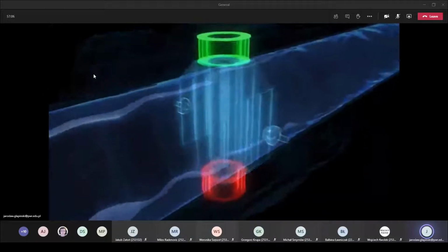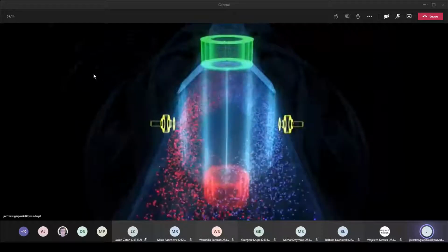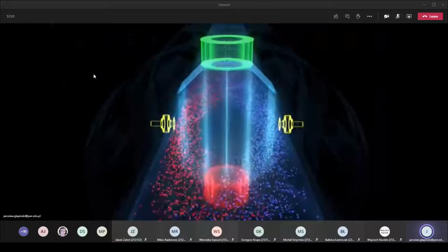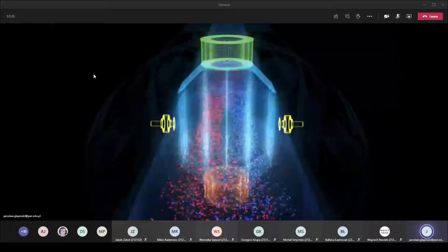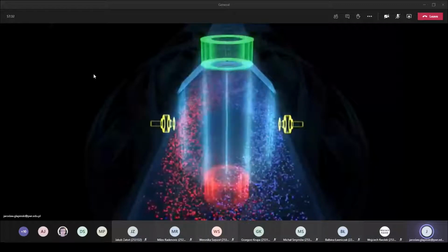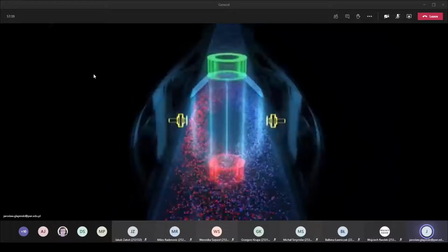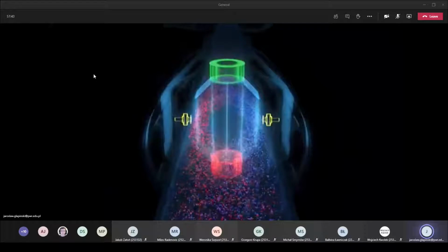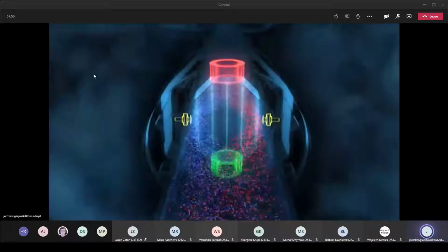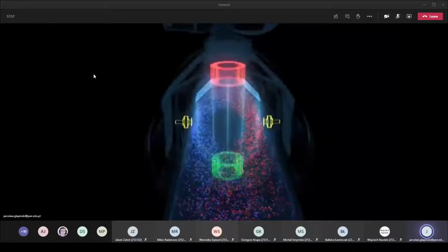The electrodes also detect what is called interference voltage, which has to be separated from the actual measuring signal. One method that has been successfully used for this purpose is to create the magnetic field with a pulsed direct current. To do so, the polarity of the magnetic field is alternately reversed, illustrated here in slow motion. The voltage picked up on the measuring electrodes now constantly changes in polarity. As a result, all constant interference voltages can be eliminated, for example, electrochemical effects in the liquid, or external electromagnetic fields. Thus, the size of such interference voltages has no impact whatsoever on the actual measuring signal. The advantages of this are a stable measurement and a stable system zero point.